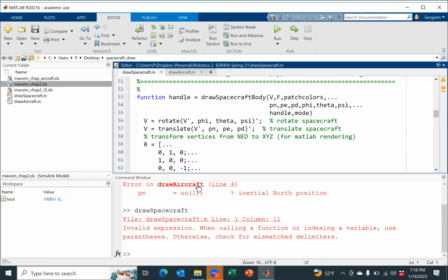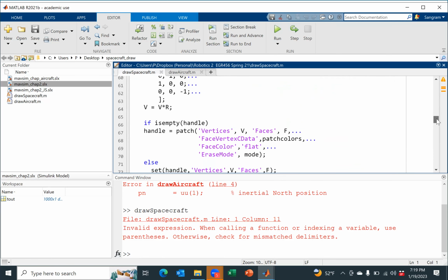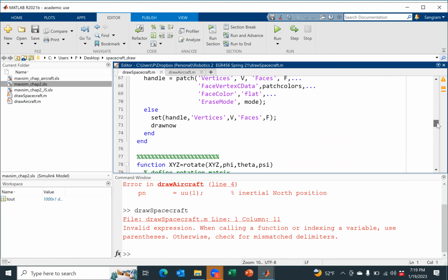That's why you have this transformation matrix. Can you see? You have a one here, indicating that your north is down and MATLAB X, Y are flipped. And can you see the Z axis is negative because you're down, your axis are down positive, but MATLAB's going up is positive. So go down, then draw now.